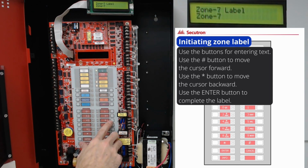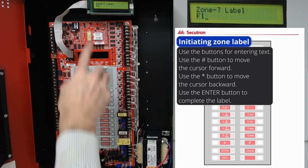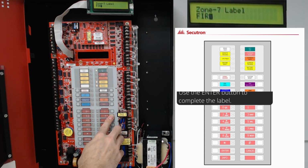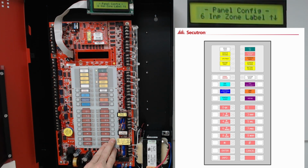For example, if we wanted to call zone 7 fire, we'd have to hit the 3 button 4 times for the F, pound to move our cursor over to the right, hit 4 times for the I, pound to move our cursor again over to the right, 7 3 times for the R, hit pound to move the cursor over to the right, and then finally 3 times for the E. And again, our pound to move our cursor over to the right. Once the desired label has been added in, we can hit enter and cancel, and that zone will now be labeled fire. If we hit cancel again, we'll go back out to our panel config options.